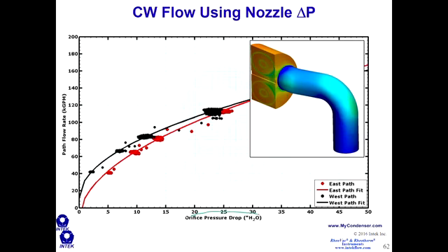You can see here's the pressure drop for some DPs that we installed for a customer, and the flow rate per path. I don't think this water box corresponded to this curve, but nonetheless. That's another nice thing about this differential pressure method: you can get the flow rate for each path through your condenser, and not just the total flow rate going to 2 or 4 paths in a condenser.